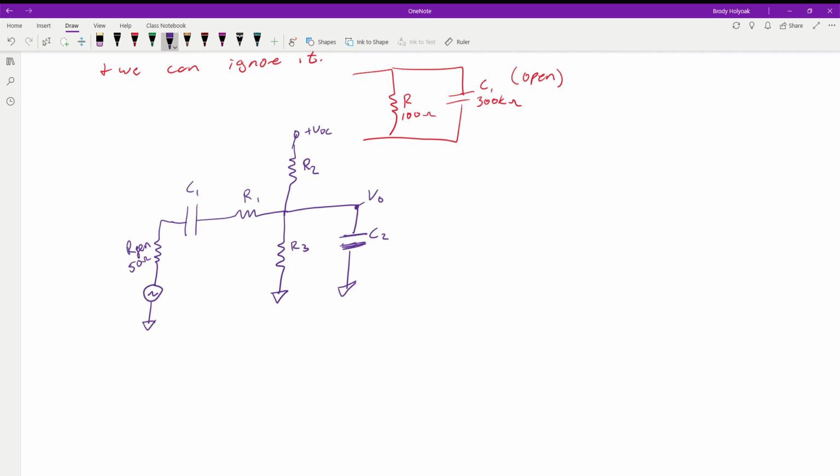So now let's put in some values. R2 is going to be 430 ohms. R3 is 510 ohms. Capacitor 2 is 5.6 nanofarads. Resistor 1 is 620 ohms. Capacitor 1 is 1.814 microfarads. And our generator is going to be putting out 6 volts peak to peak at 3.994 kilohertz. So basically we were trying to set this thing up to 4 kilohertz. This is as close as we could get it. That's the value we're going to use to calculate this.